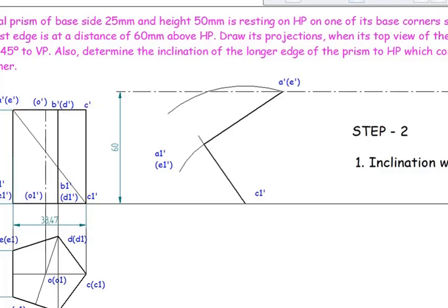Now from here to here again I'll just go for arc by center point, or else you can use a roller scale and draw lines parallel to the base and the lateral edges, or else you can just draw an arc of radius 50, and from this point, which is equal to 38.47.